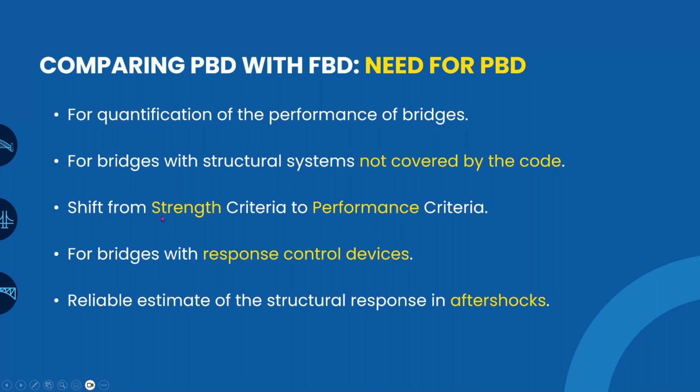There is a shift from the strength criteria to the performance criteria. For bridges with response control devices, the quantification of performance of those bridges is possible. A reliable estimate of the structural response in aftershock is also possible by using performance-based design.